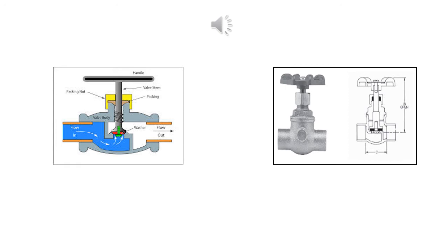The picture on the left shows you an internal picture of a globe valve. The baffle has an opening that forms a seat onto which a movable disc or plug can be screwed in to close the valve. In globe valves, the disc is connected to a stem which is operated by screw action using a hand wheel in manual valves. There are also automated globe valves which have smooth stems rather than threaded and are opened and closed by an actuator assembly.